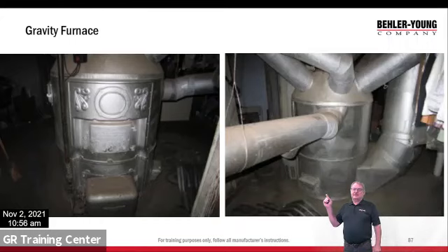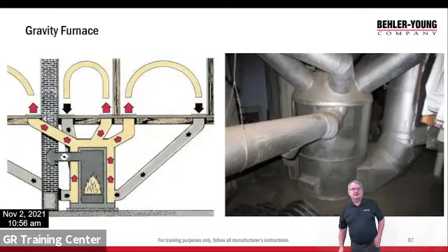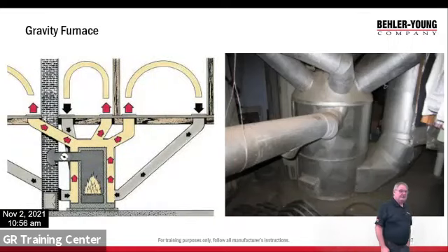You can see the little draft diverter opened to the basement, because we need dilution air, remember? Now you're an expert on dilution air and makeup air. Then you can see there are some dampers on those ducts. That's how we controlled room temperature. We can damper them down. There's a little bit better picture of it over there.